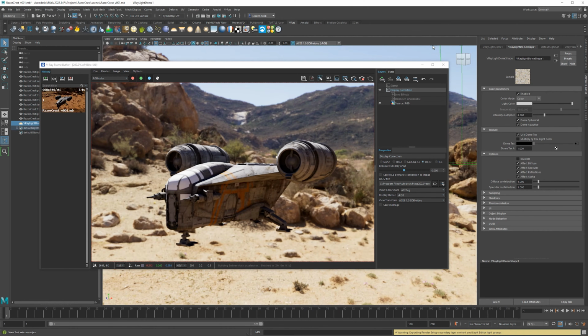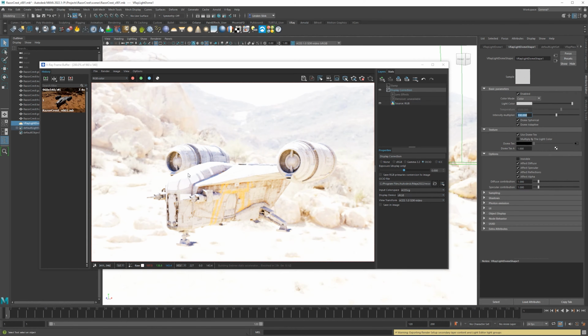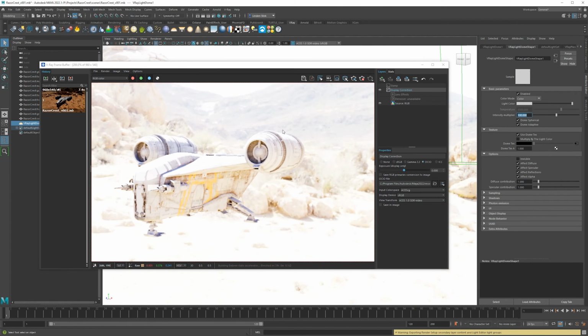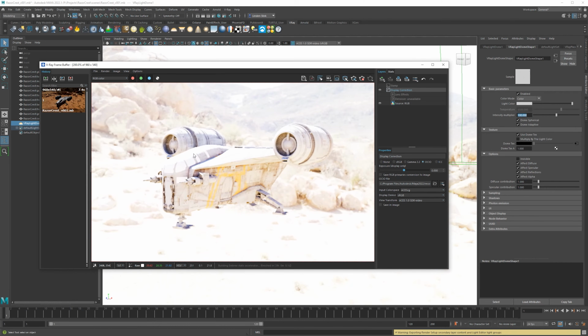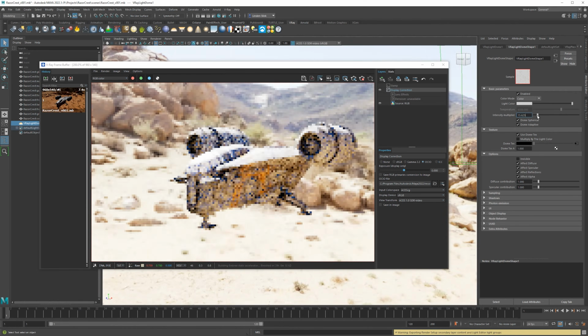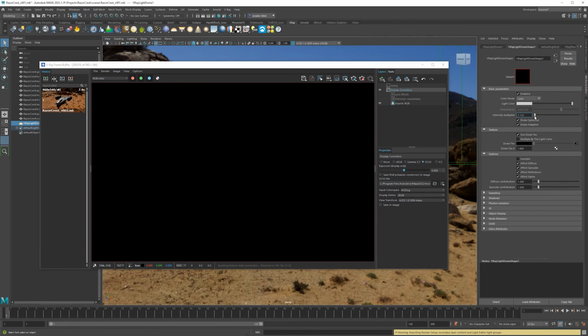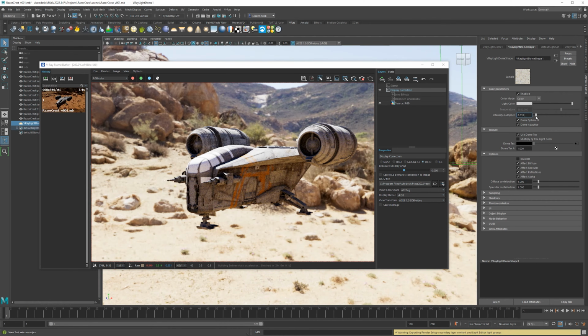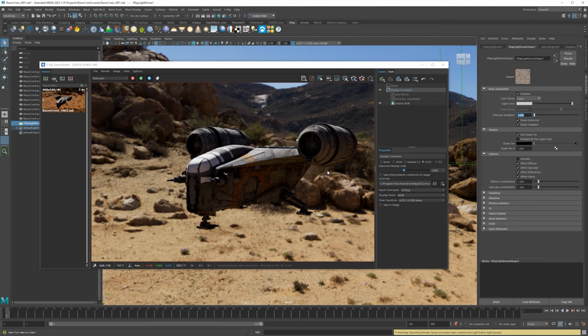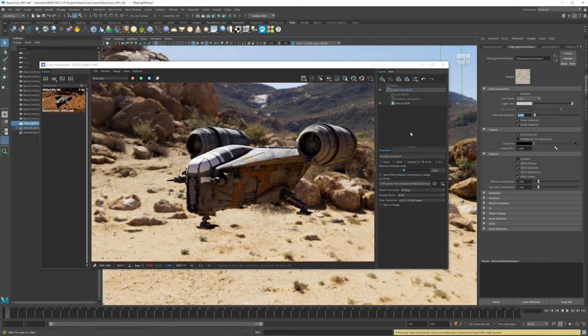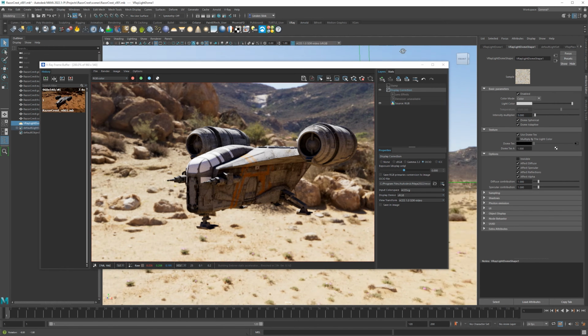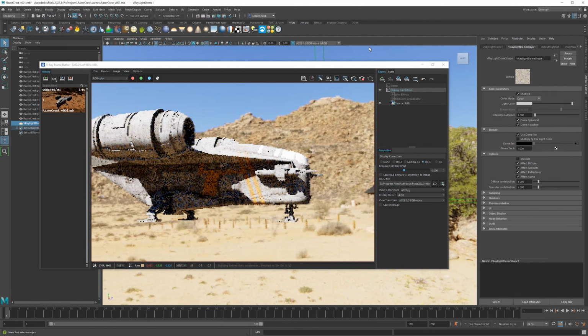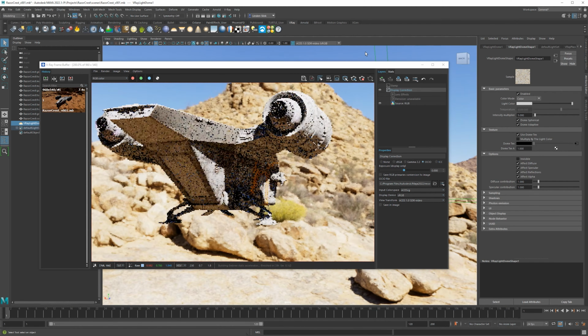So basically sRGB 8-bit. So this is great, that you can say, hey, I want the intensity of this to be like white, but it's never going to completely blow out, really. The values here are always going to be 1 for the hotspots. Okay, obviously we don't want to go that crazy with it, but we do need to bump it up because by default it's way too dim. So we do want to make that a bit brighter so we get some bounce light. So maybe a value of 4 is okay, maybe 5. It just depends. But ACES is going to give you a really nice natural look. So it might even be a little bit too bright, but hey, you can correct that later.